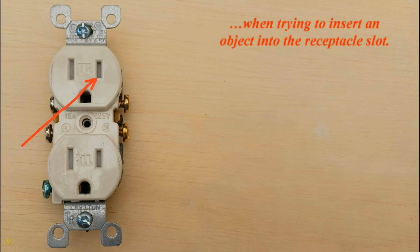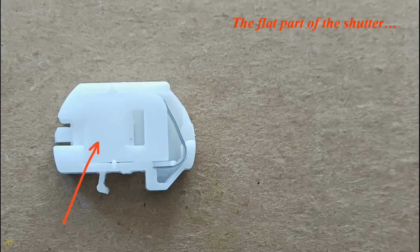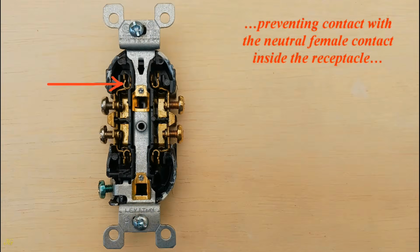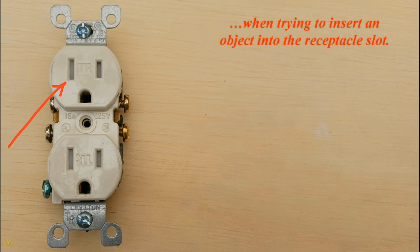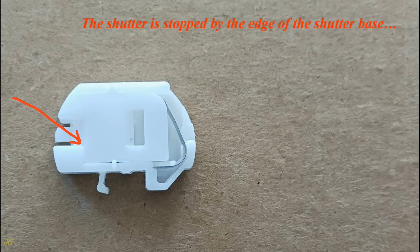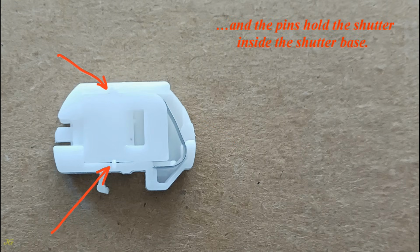When trying to insert an object into the receptacle slot, the flat part of the shutter that covers the neutral slot in the front base of the receptacle prevents contact with the neutral female contact inside the receptacle. When trying to insert an object into the receptacle slot, the shutter is stopped by the edge of the shutter base as the spring presses against the shutter, and the pins hold the shutter inside the shutter base.